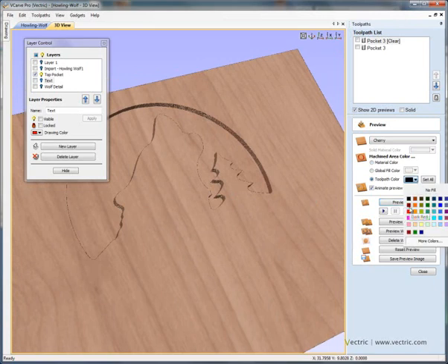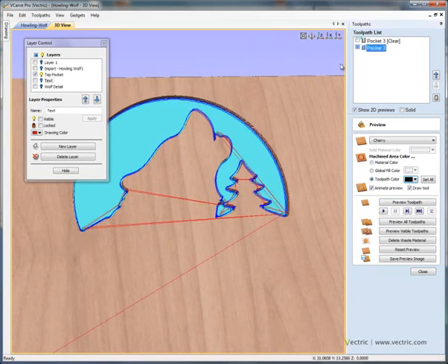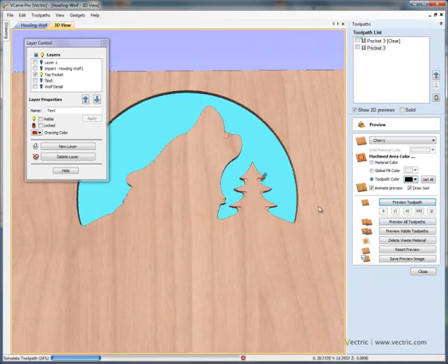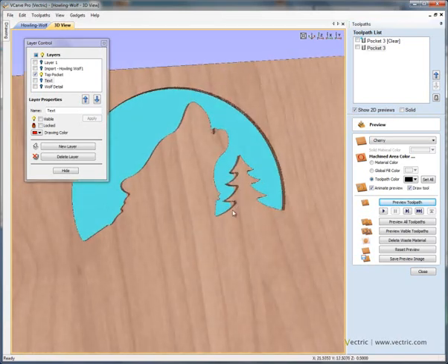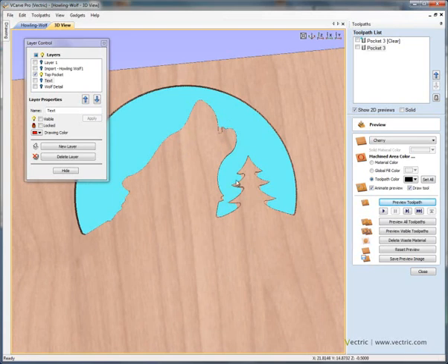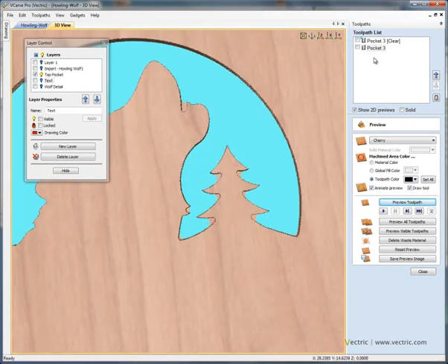Let's make this a sort of turquoisey color. And then we would change the cutter for the 1/4 inch end mill, and this will profile round and pick out a little bit more of the detail. So preview this toolpath, and you'll see that that's just profiled round. It's machined away some of the detail in the corners. You'll see in the mouth and also in the areas on the little Christmas tree there.